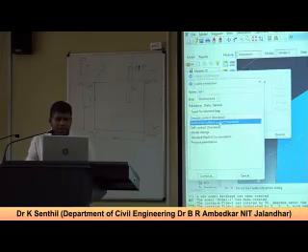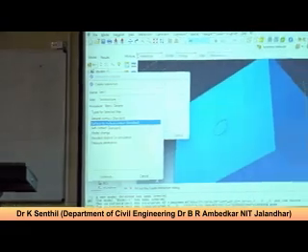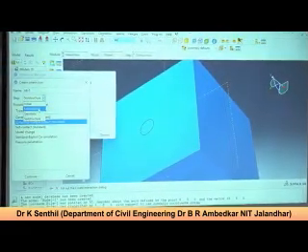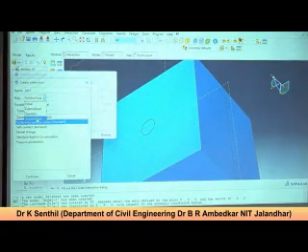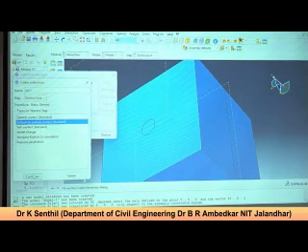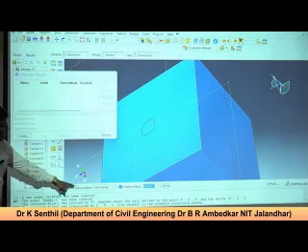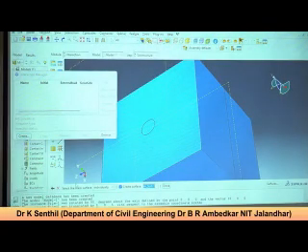So now let's talk about the surface to surface contact, soil structure. Here you can see there are three things we have selected: the external load, geostatic, and the soil structure. So these three things you can take. Soil structure first, continue. Now it is asking you to select the master surface. So let's treat this pile surface as a master surface.